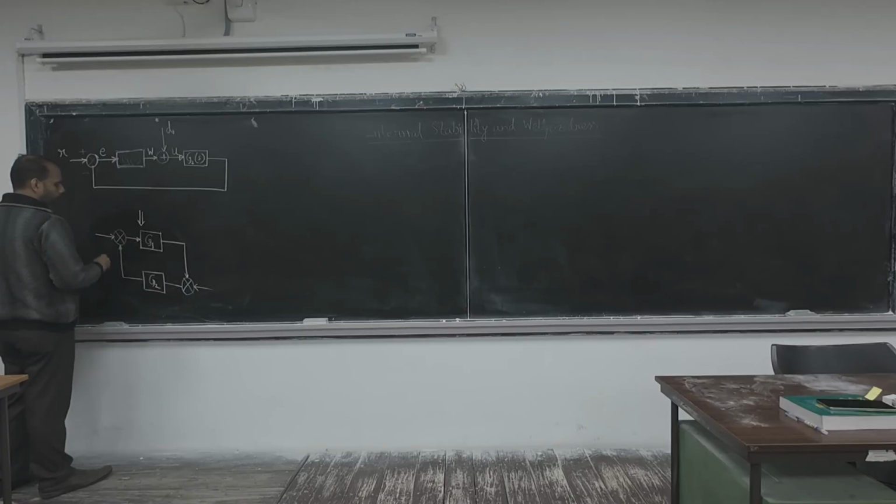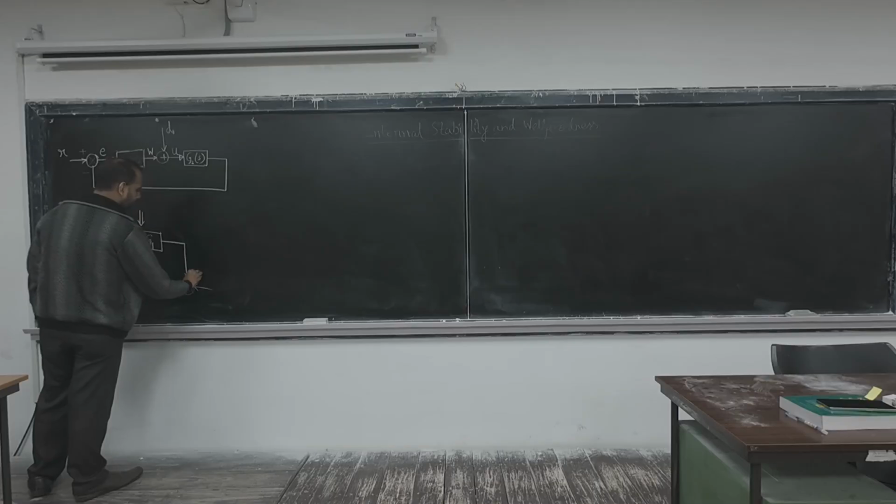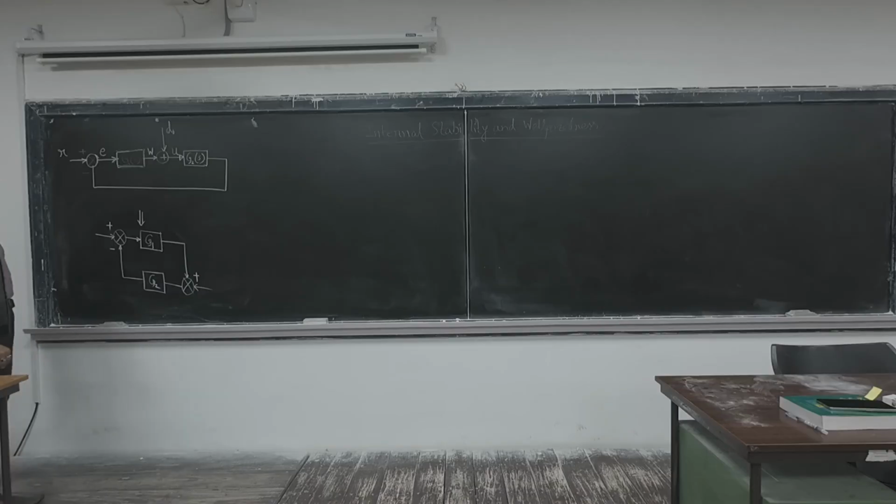Okay. So for the same example which we considered, 1 by s square minus 1 and then s minus 1 by s plus 2, you will find one of them will become unstable. So for it to belong to RH infinity 2 cross 2, you have to check whether each of the transfer function elements belongs to RH infinity. Yes.